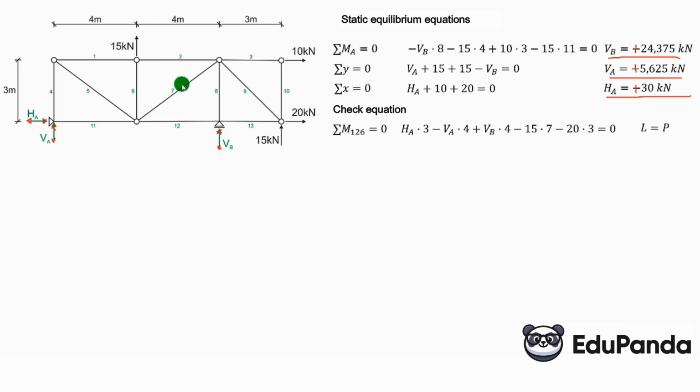Because, for example, many problems with the Ritter method involve calculating reactions in the members, and usually the middle members are given. Because the Ritter method is most useful when we need to calculate forces in specific members, and most often if they are located in the center, if we were to approach it through the equilibrium of nodes, well, here we need to balance the first node, then we have to balance this one, then we have to balance this one. Only then will we have that force. So we make one cut. We have 3 unknowns and 3 equations, the sum of moments for 3 Ritter points, and then we can directly calculate the 3 bars we are interested in, the forces in them.